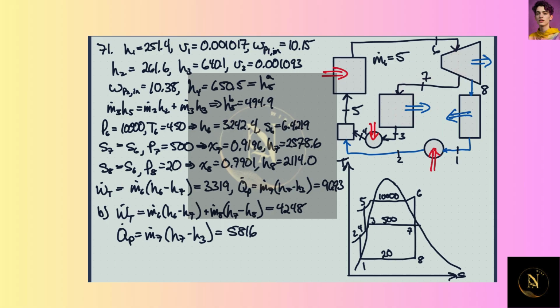So then for the process heater, in this case, M7 is also M6 because M8 is 0. And so in that case, we're getting process heat out from the process heater. We're getting about 9.7 megawatts of heat coming out of here. So that's the case where this is all shut off. All these blue things have 0 flow in them.